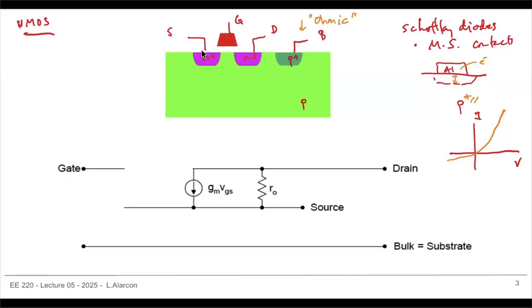So if the depletion region starts becoming less and less, then what really happens is, okay, instead of a diode characteristic, you start getting an ohmic contact, right? So that's why every time you contact, let's say, a substrate, you will always see a P plus type region connected to the P, because you don't want to get a diode there, right? You want to get something like a resistive contact.